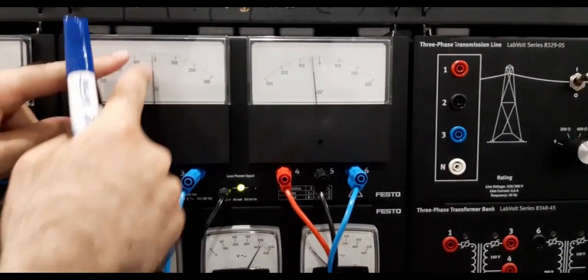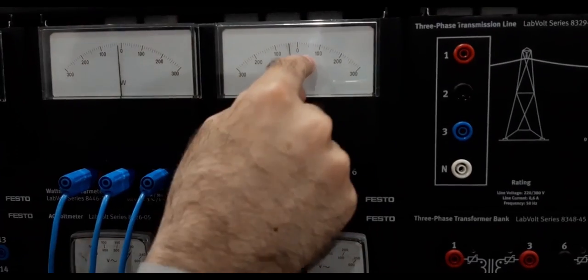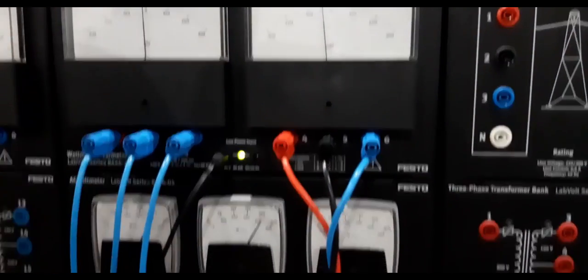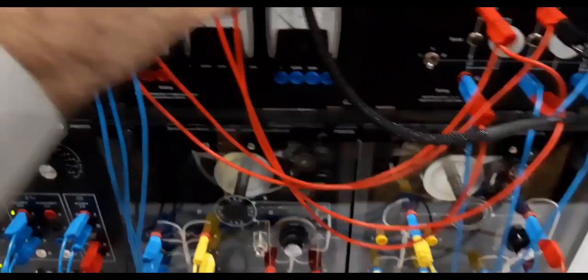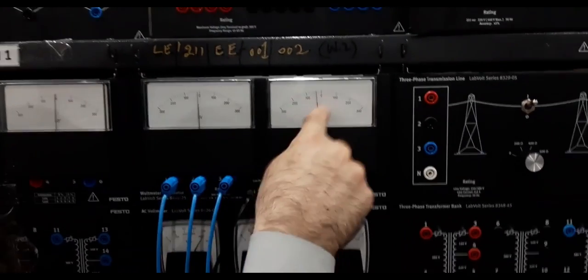So the active power is positive, or it is almost 0. It does not vary with the field current. It must be positive because it's a generator. So by varying the field after synchronization, the generator still remains a generator. All that changes is the reactive power.